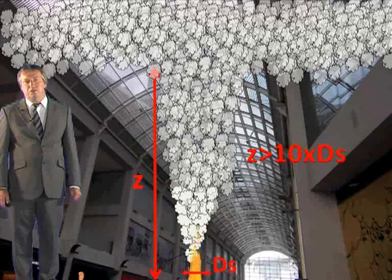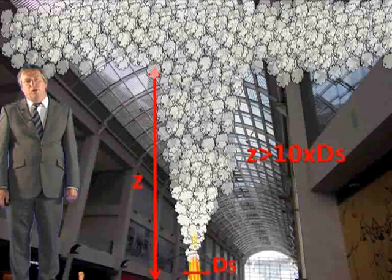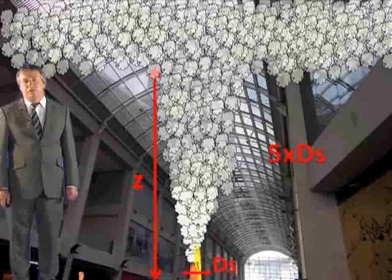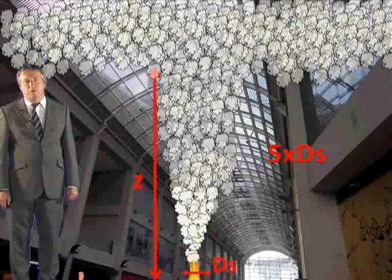Some advice seems to indicate that the far field model gives more accurate results for the situation where Z is greater than 10 times the longest dimension of the source fire. But the far field model is used for clear layer heights far less than this, and there is little doubt that the equation can probably be safely used to predict mass flow rates for clear layers down to clear layer heights of about 5 times the longest dimension of the fire source.